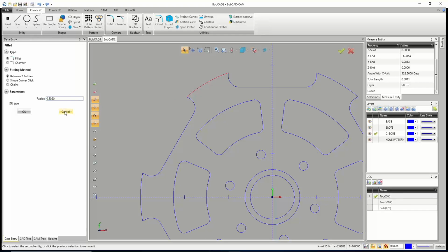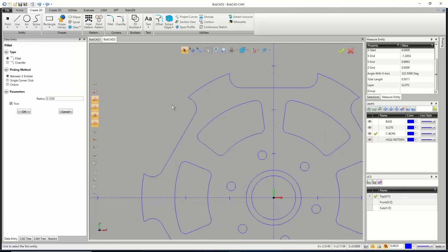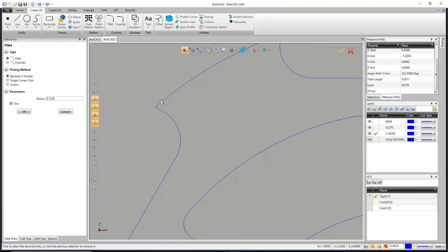So the way that you have to do these ones is you have to set up your fillet size. So we'll go 0.25. Actually, let's go 0.125 on these. We could try and put our 1/8 inch fillet on there, and you'll see it really has to go pretty much down that far for it to work. That's kind of how it shows it. Not going to work. But if I go from this arc to this line, I can fillet it. And it leaves that little section there.